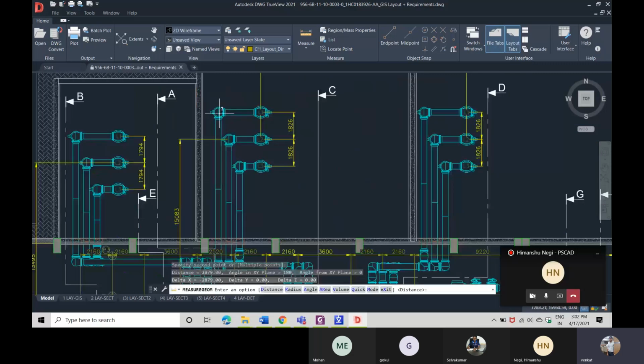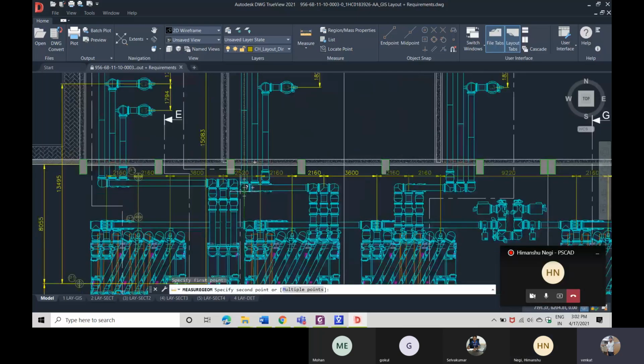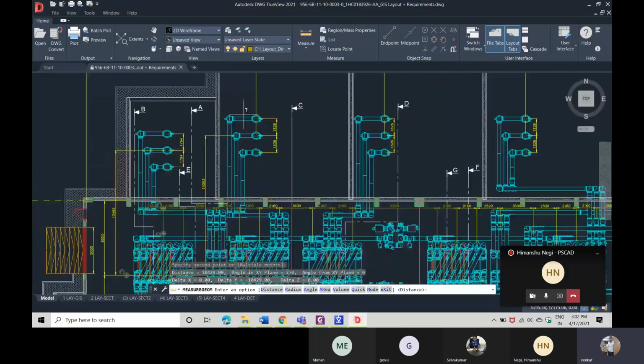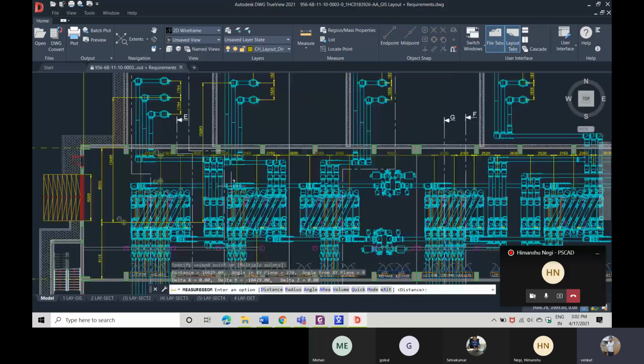Other than that, here we have an L bend, an elbow, right? So we have to take the measurement from this point to the other elbow where we are going to move. Here, can you see this? There is some elbow. Up to this point we have to measure it, and for this location we have to model it as some surge impedance, for this particular distance. Like this, you have to model the complete substation.